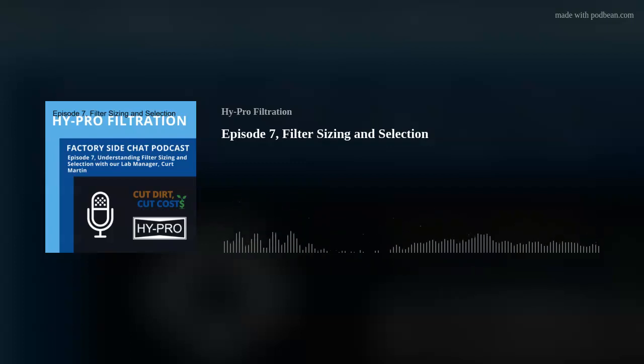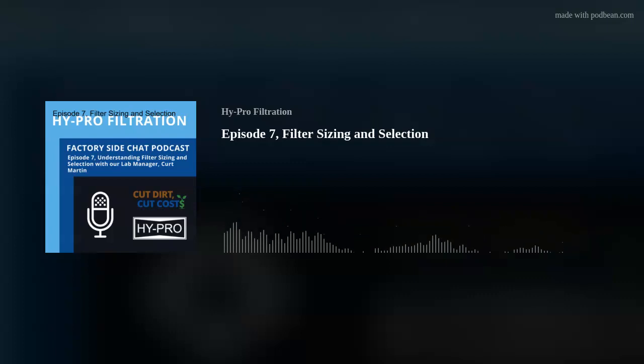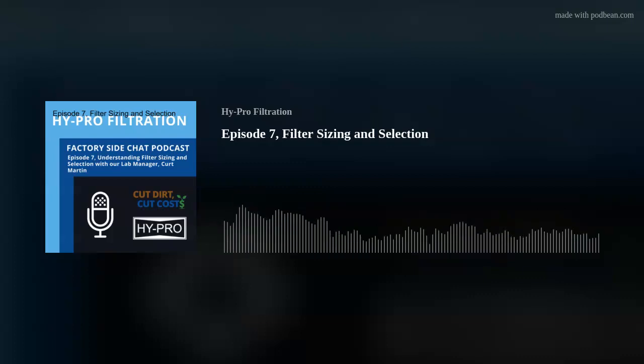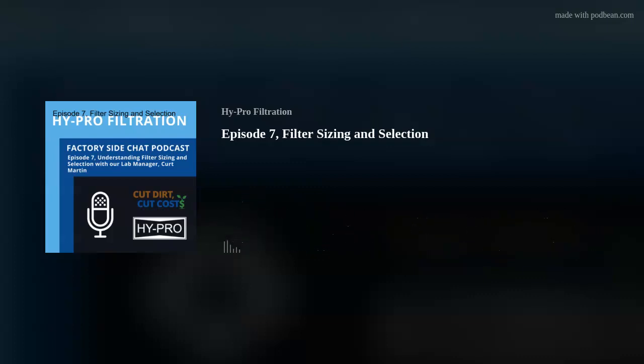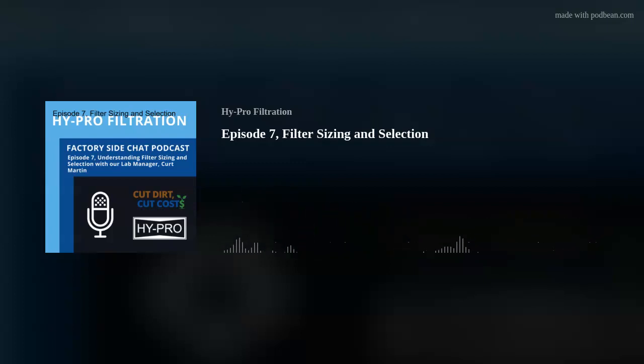That's good information. So whenever you are asked to size a filter cart, what are some of the things that you ask to size the filter cart properly for their application? So for filter carts, the information I ask for is very similar to if I'm just sizing a housing: fluid type, temperatures, the flow rate they're looking for, the micron ratings.